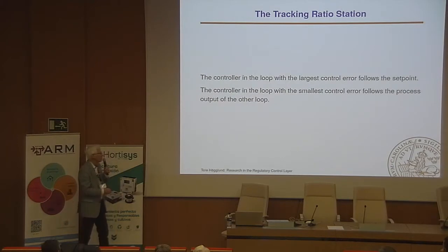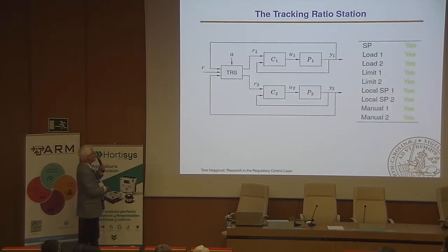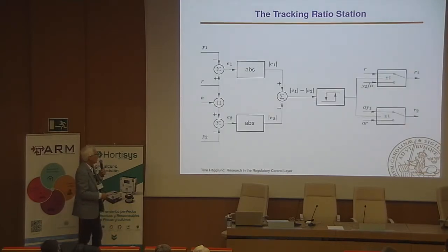In fact, this is the only slide I could have shown on this one, but I have some more. This is a symmetric approach. The master and slave roles are switched all the time. There is no one single master, one single slave. You can implement it using standard blocks in a DCS system. I will show you an example.